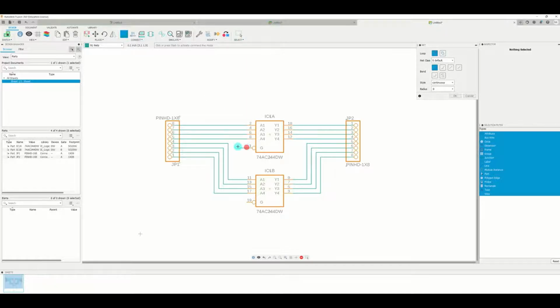So again, select, you click, move it down, click, and then you can move it here. But what you do is you would need another jumper. We need one more jumper or one pin for this if we want to have these two connected together. So with that you can cancel, but then there's no connection. Okay, so click, of course you select the net, click, click, and then you can cancel.